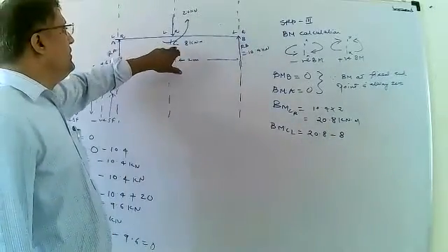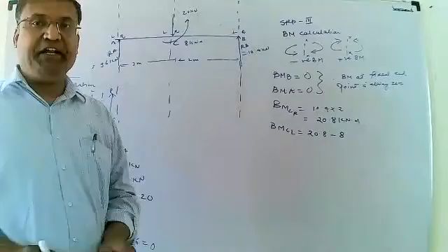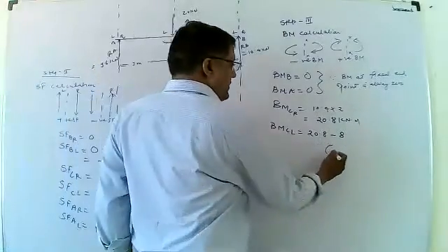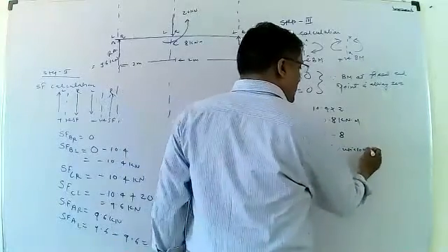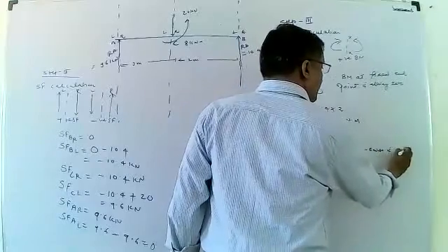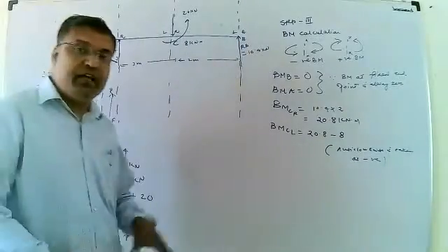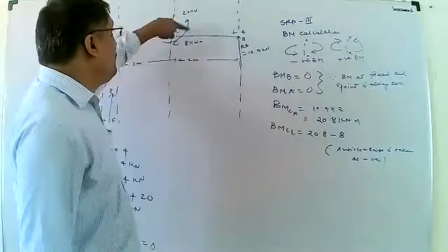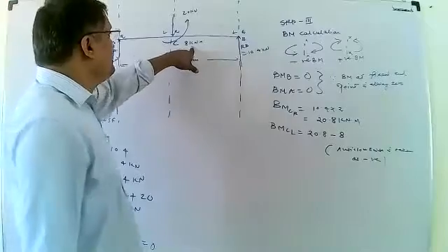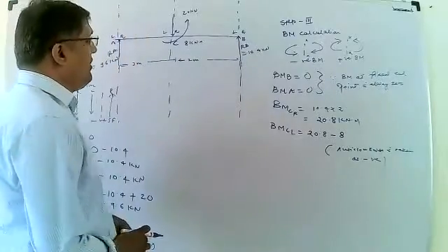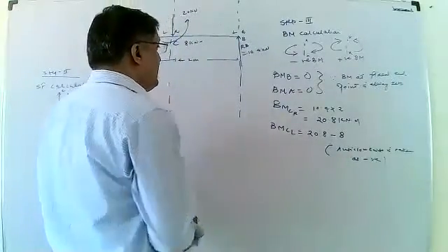Here, if you see, the moment is anti-clockwise, then anti-clockwise is taken as negative for a couple. That moment is taken as negative. This is an anti-clockwise moment, and its value is 8 kilonewton meter. Then here you will get the value finally 20.